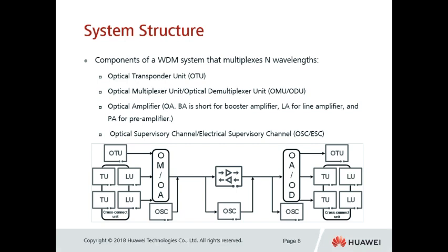And you can see this time we announce another problem for you. In the middle of this system structure, we have one regenerator unit station, that is the optical amplifier unit. This optical amplifier only amplifies the power for your service. It does not detect your service, right? Because it does not detect your service, the ESC overhead cannot be detected.